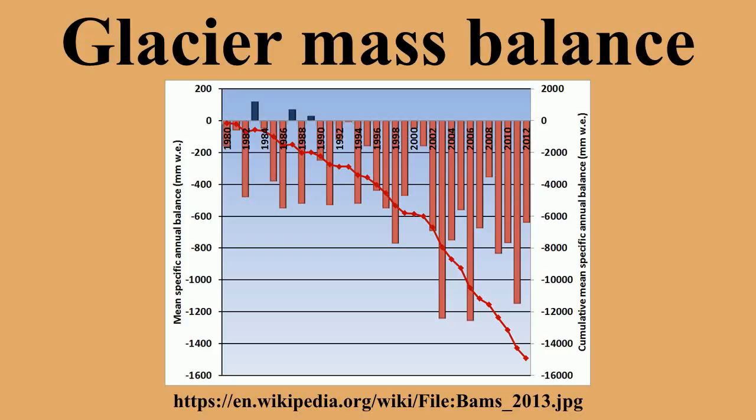Regardless of depth measurement technique, the observed depth is multiplied by the snowpack density to determine the accumulation in water equivalent. It is necessary to measure the density in the spring as snowpack density varies. Measurement of snowpack density completed at the end of the ablation season yields consistent values for a particular area on temperate alpine glaciers and need not be measured every year.